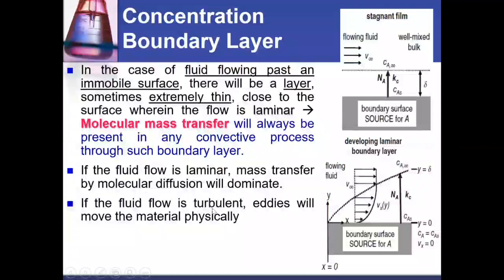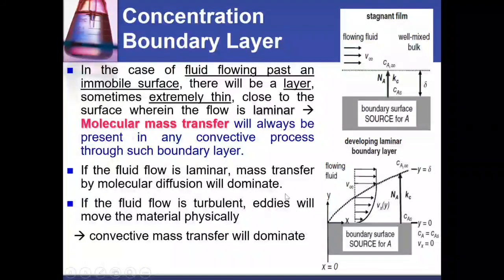If the fluid flow is turbulent, yes, Abdulaziz. If the fluid flow is turbulent, as you know from fluid mechanics, you will have eddies, and the eddies will move the material physically. They just detach the material from the surface and move it physically with them. In that case, convective mass transfer will be dominating the mass transfer.